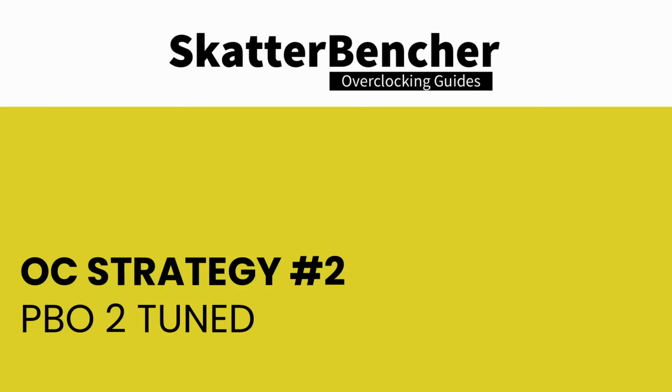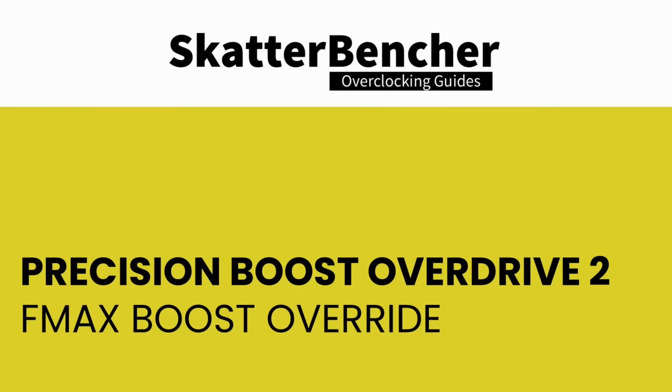In our second overclocking strategy, we start our tuning work with the tools available in the Precision Boost Overdrive 2 toolkit. More specifically, we'll try to use Fmax Boost Override and Scalar. Fused Maximum Frequency, or Fmax, is one of the limiters governing the Precision Boost algorithm. It basically defines the maximum allowed frequency of any of the cores inside your CPU.